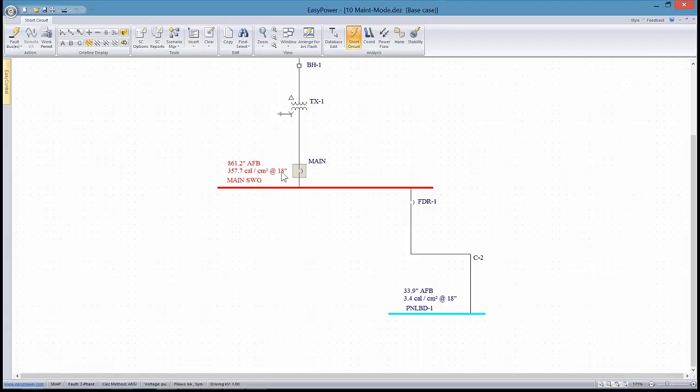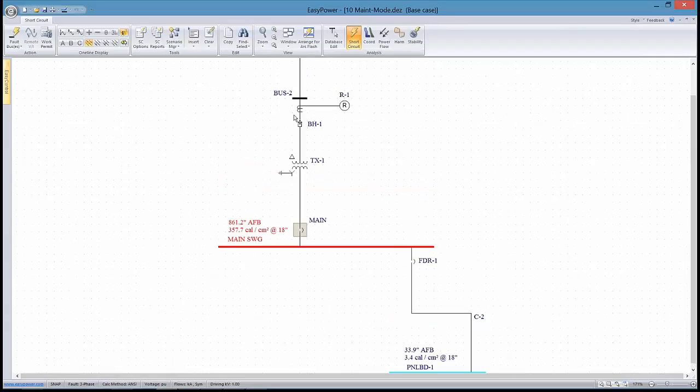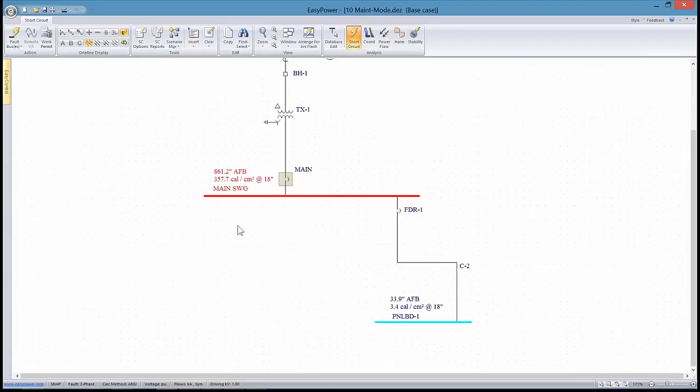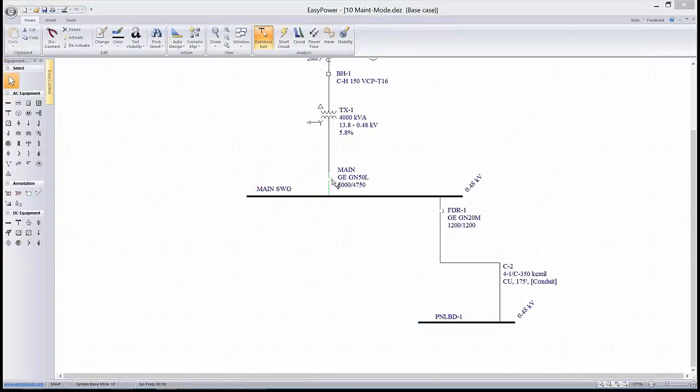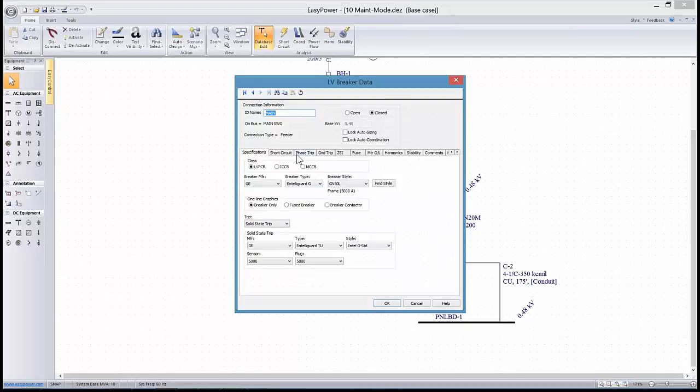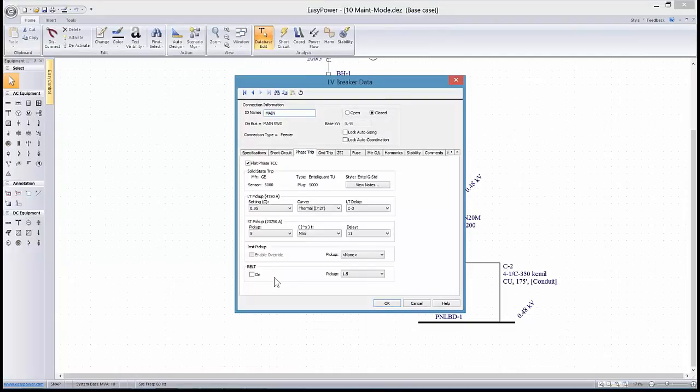Maintenance mode is a feature of more modern breakers that can do a setting after the breaker has been activated. It's called maintenance mode or reduced energy let-through, and it's part of the setup of that device when you're drawing the one-line diagram.